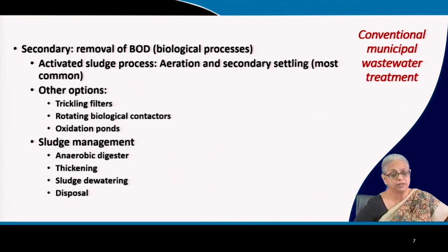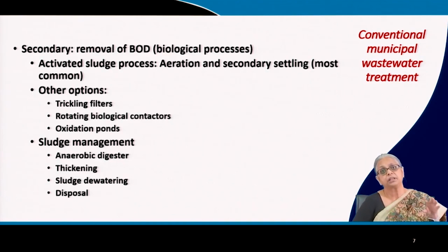Then we come to secondary wastewater treatment. Secondary wastewater treatment has a single objective, and that is the removal of BOD. So whatever BOD is present in the initial untreated water has to be removed as much as possible in these biological